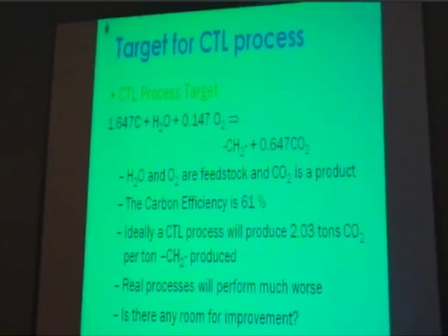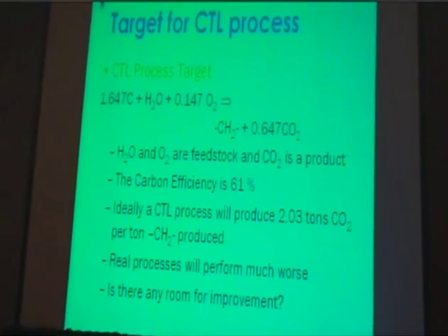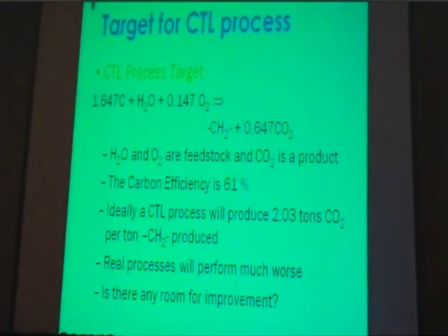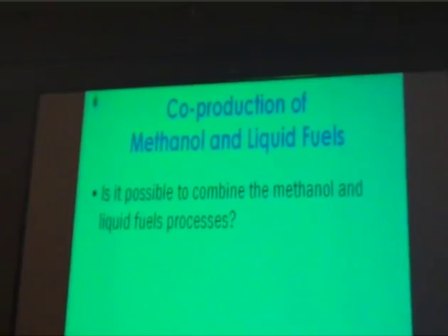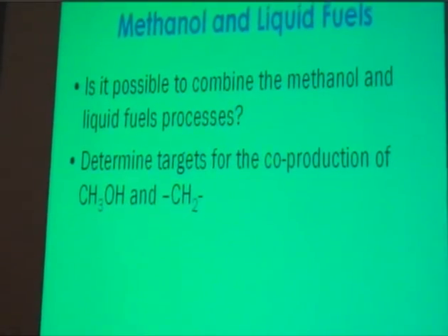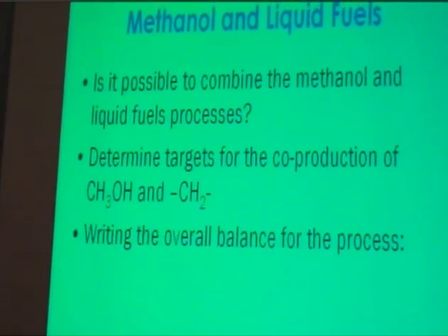It doesn't matter what flow sheet you put in, it doesn't matter how fancy your catalyst is, you're not going to be able to beat this rule, because this is defined by the overall rules of thermodynamics on the overall process. What if we take a look at the combination of producing methanol and liquid fuels in the same process, and look at determining some targets for the co-production of methanol and CH2?